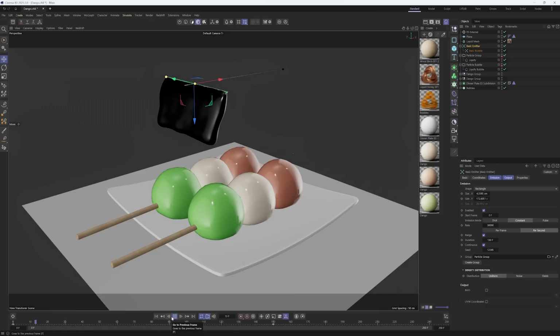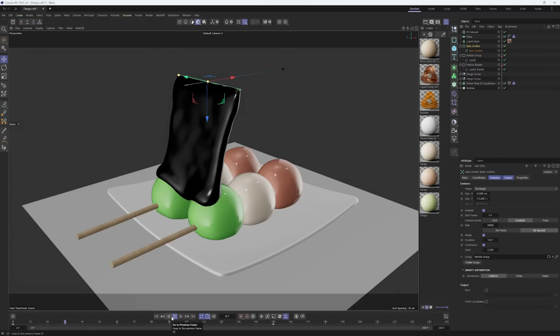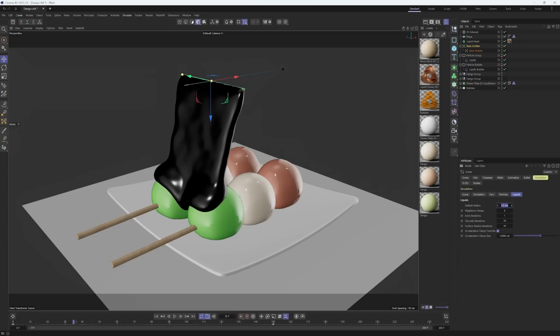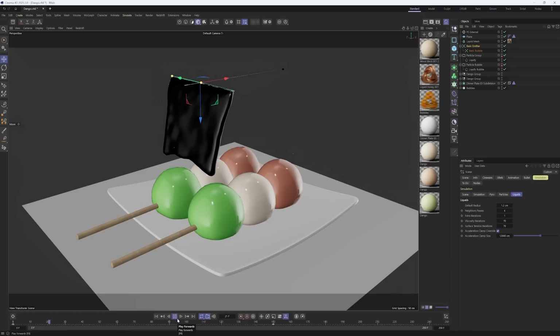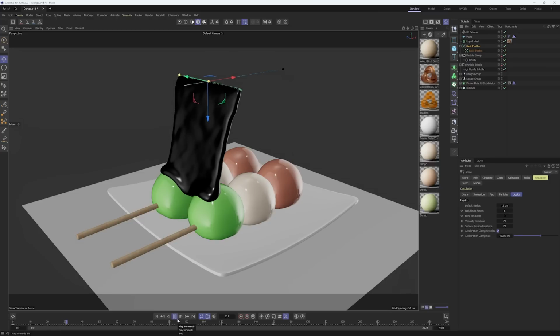So didn't change anything really much at all, just added a lot more particles, and you can see we no longer have those little holes. Now this is a little bit thicker of a sim, so we can go in and maybe bring the default radius down to like 1.2. And if we have enough particles being generated, it shouldn't matter much because we will not have those holes, because we have so many particles filling in those gaps.